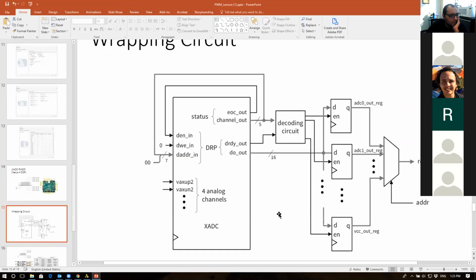Then internally, what we're gonna do is basically make a wrapper around the Xadc, so it will help us to start producing outputs on the 7-segment display. Or you can make UART communications, or you can even build the circuit on the side with the potentiometer. And when you change the potentiometer, you push it into the Xadc, and the values will be flickering on the 7-segment display or VGA or whatever, right? How you're gonna do it is basically like that.